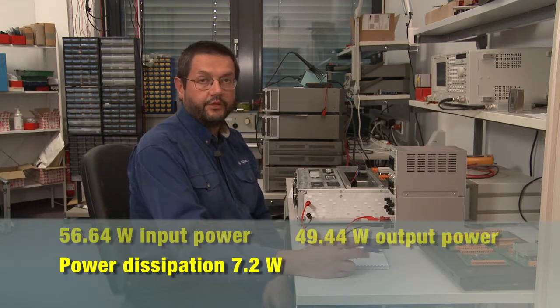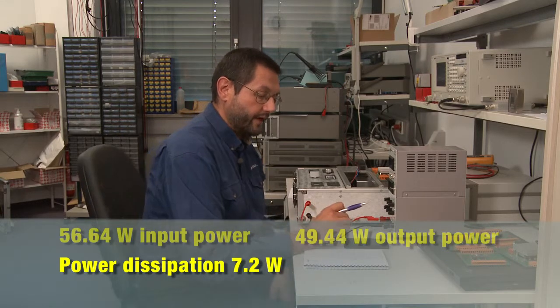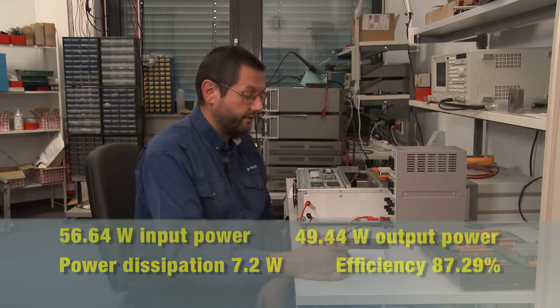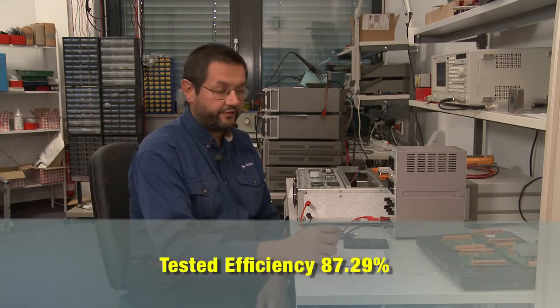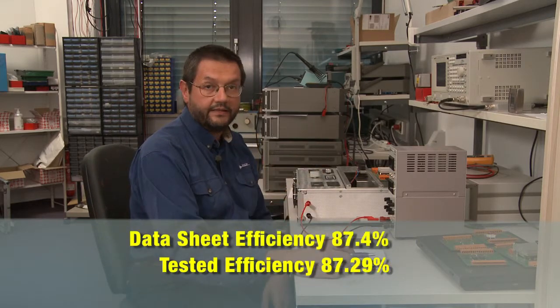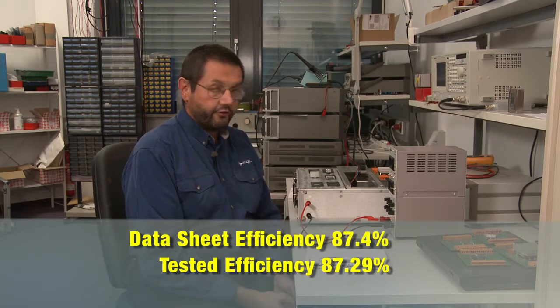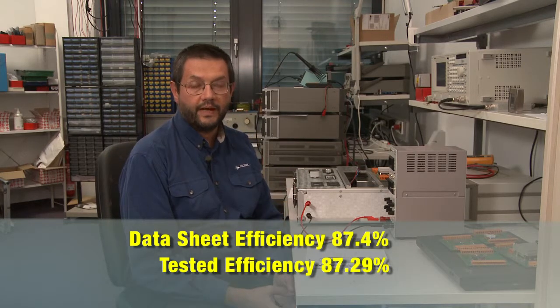The efficiency of the module is the ratio between the output power and the input power. So we have 49.44 divided by 56.64 gives us an efficiency of 87.29%. The efficiency of this module, as specified in the datasheet, is 87.4%. So that shows a very good consistency between what is specified on the datasheet and what we have calculated by an experimental method.